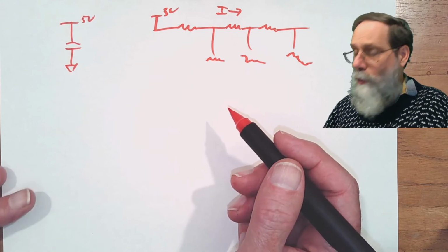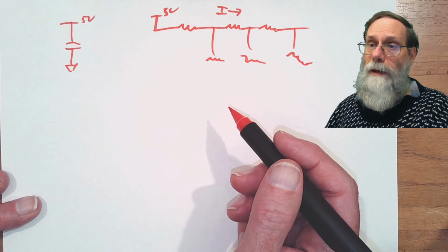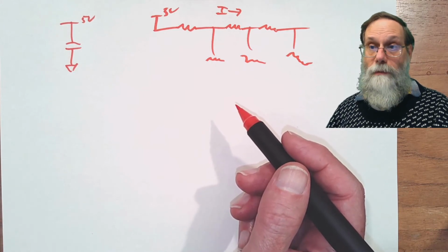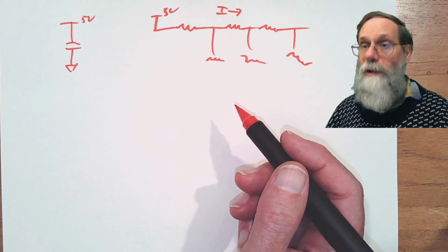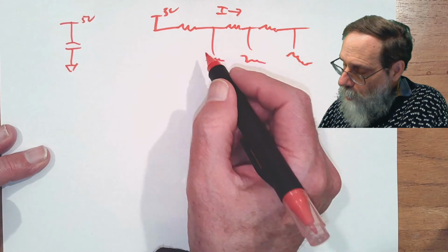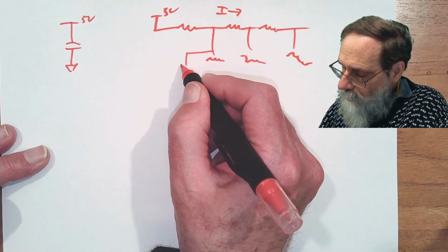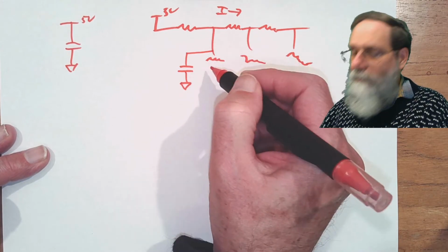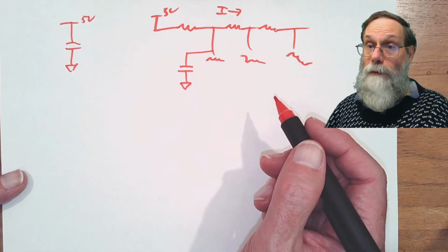And this means that the modeling gets much more complicated if you have to really worry about that. So what a lot of people are trying to do, however, is to make the 5-volt, or whatever your power supply is, look like it's constant, so that as far as your circuitry is concerned, it can treat it as a constant voltage. And so what is often done is to put a capacitor here where you're actually trying to look at the voltage.